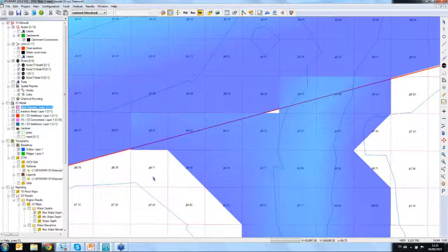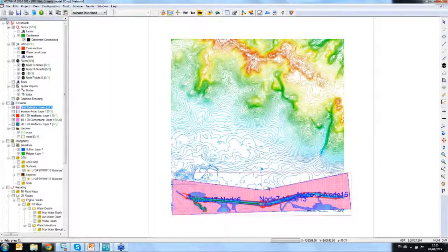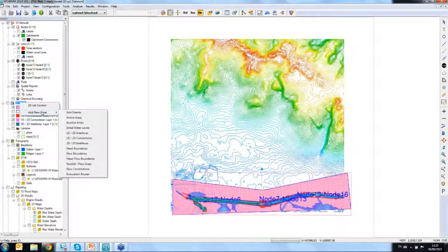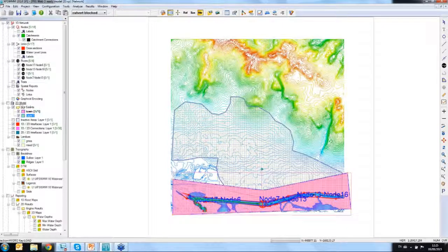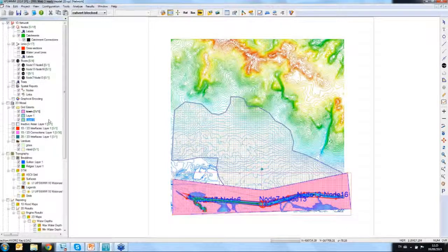There's a supplementary that's come in on that because some folks are working with mixed catchment, so they have some flooding in like an urbanized area, but they also would like to incorporate some of the rural runoff aspects as well, like you're showing there. So could you have different grid cell sizes, if you like, so more dense where the critical flooding is in the urban part, but then larger grid squares where it's not quite so important, if you know what I mean, in the rural aspect. You can create more grid extend layers. So at the moment we have 1 layer, but we can create more layers, and we can then draw.